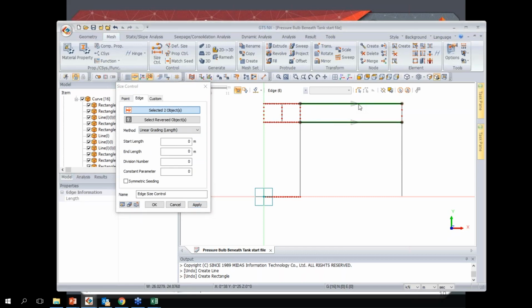You can see there's actually a directional line. And I want to select the third one. But if I select it now, given the orientation of the geometry, the program automatically assumes a clockwise direction. So since it's in the opposite direction, but I actually want them to have all the same distribution, I can unselect, and then I have a second option to select lines, reverse to the original.